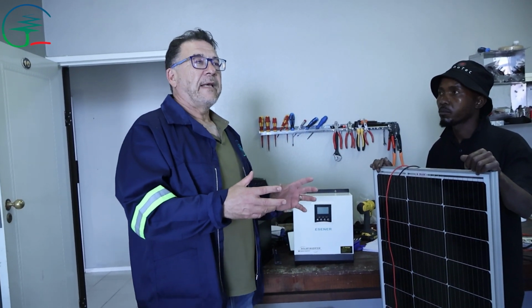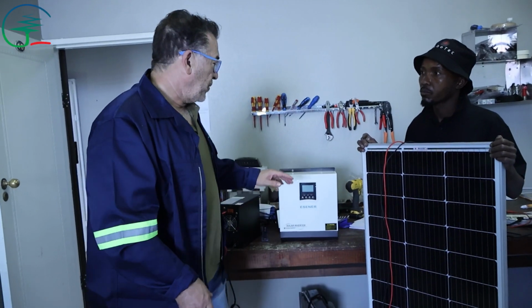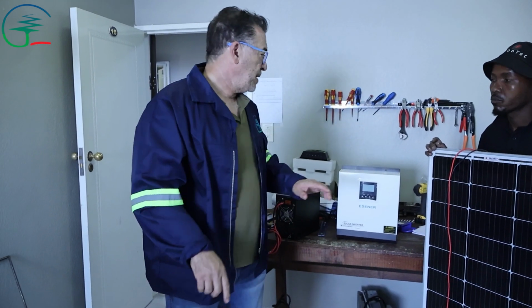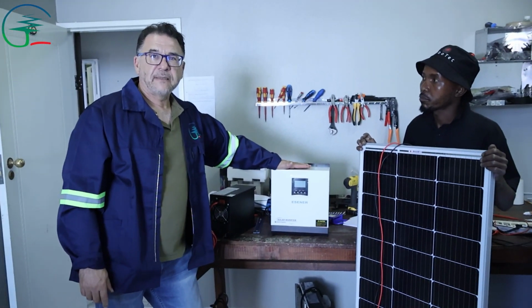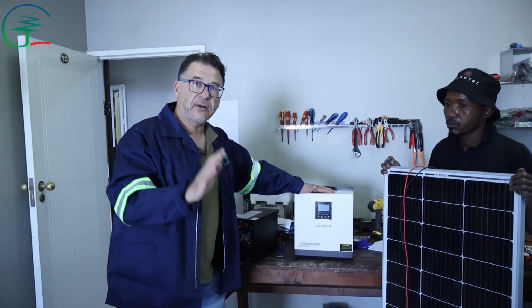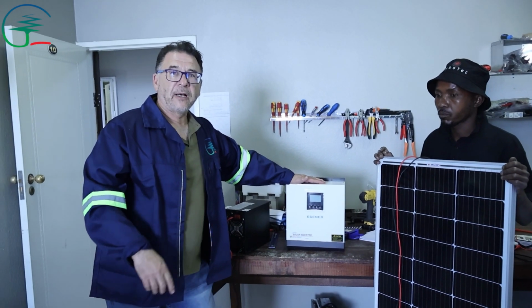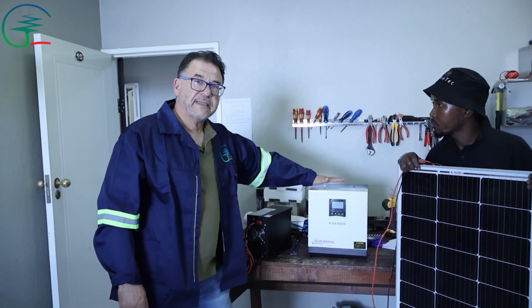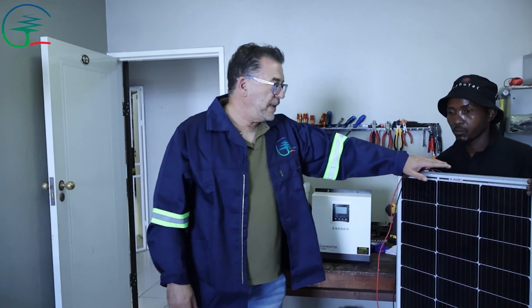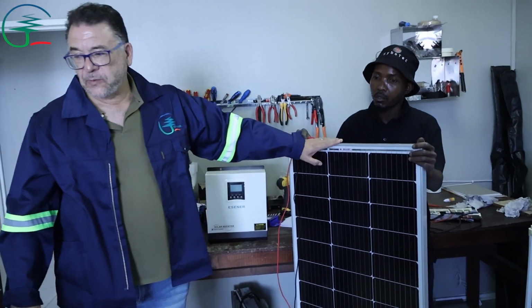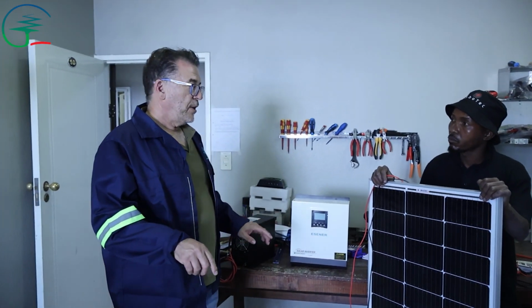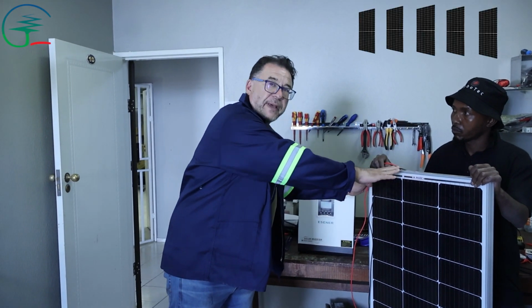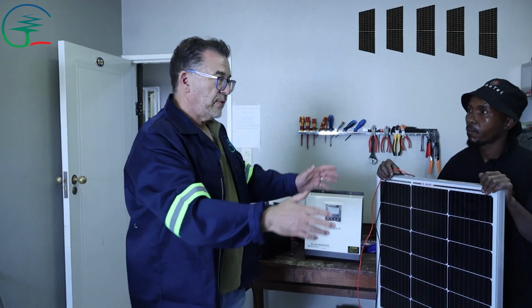That doesn't mean you only need to use 5, because there's another calculation we can take into account: the amps. The max charge current, assuming only solar is going to charge your batteries, is 80 amps for this inverter. We saw the IMP current of the solar panels was 8.4, and then we get a value of 9. That means you can have 5 of these solar panels in series.